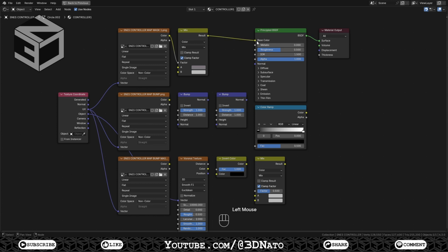Notice, as we are using a black and white mask, the black parts are making the mix color show only color A and the white parts only color B. Connect the bump mask map image texture color to the second mix color factor. This bump mask will control which areas will show the colors A and B. In this case here, to control which parts will use a Voronoi texture and which parts don't.